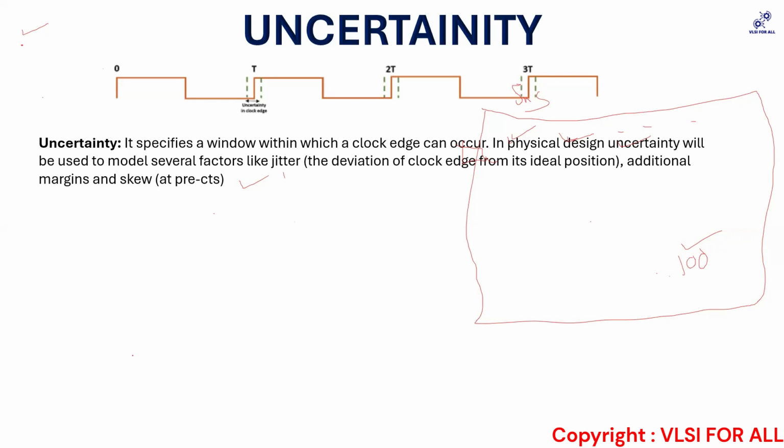Okay. For example, what is actually a setup delay? Can anyone just tell me in very short, what is actually a setup? Well, the minimum time the data should be stable before the application of the clock. Okay, so before the clock arrives, your data should be present over there, correct? Yes. But when the tool is doing this, you have this definition stating that your required time has to be greater than your arrival time, correct?